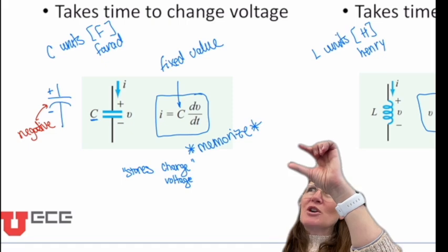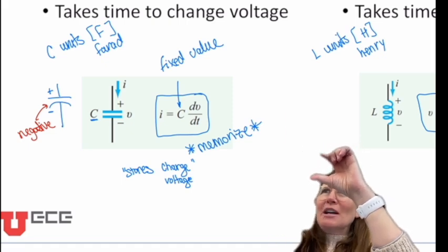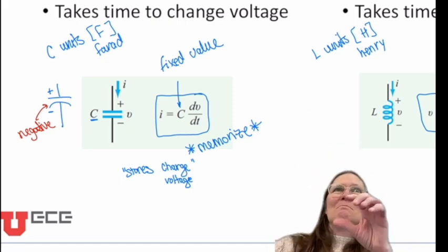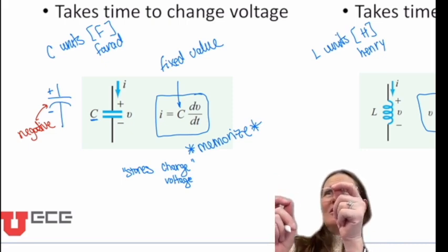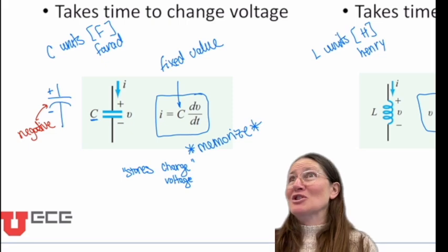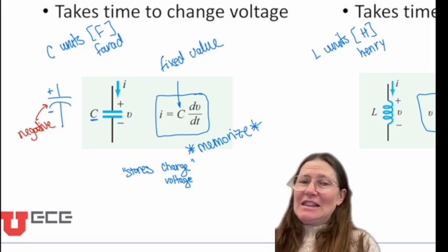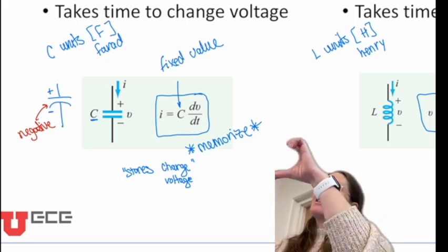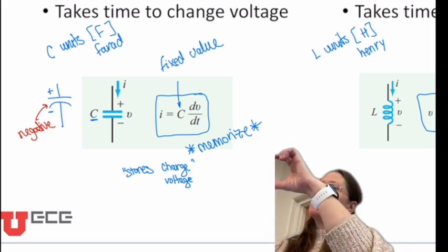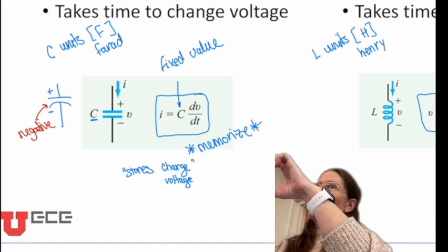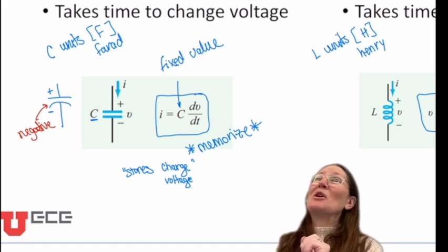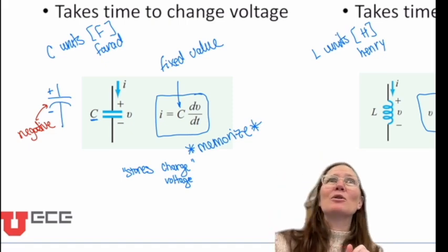They're usually the bigger capacitors, and you will see a big minus around the minus side on them. So you'll know which lead on that capacitor you need to hook up. But just note, that is one way. Another thing is if your capacitor has one side shorter than the other, one of them is going to be negative. So that will be a polarized capacitor.